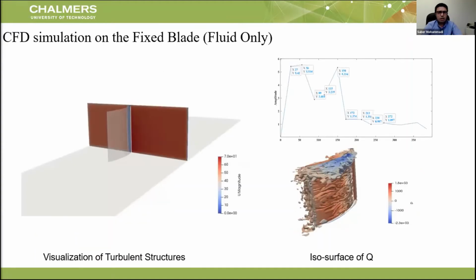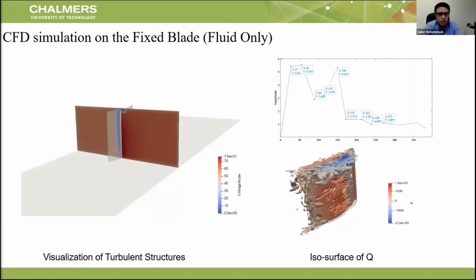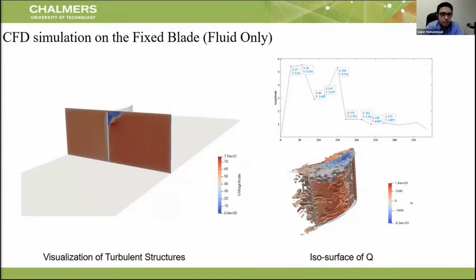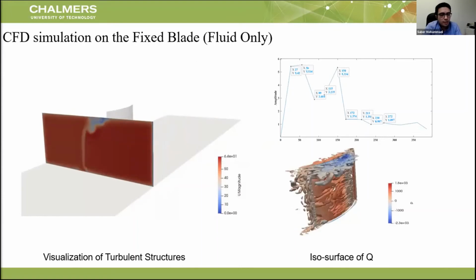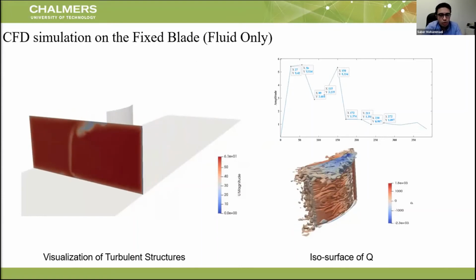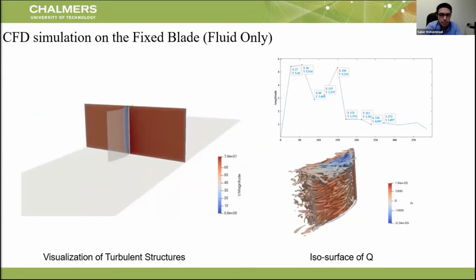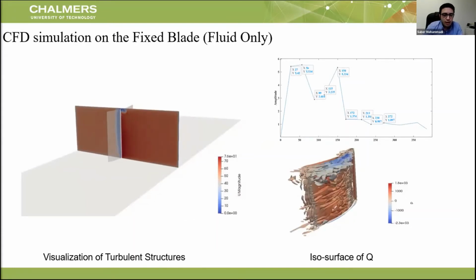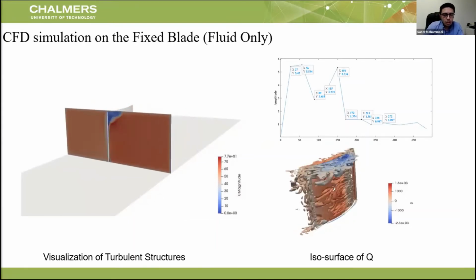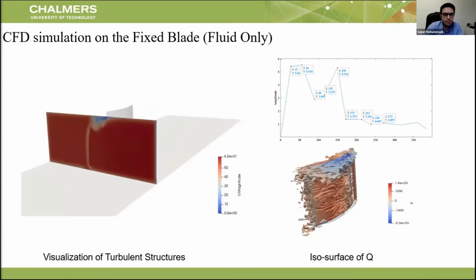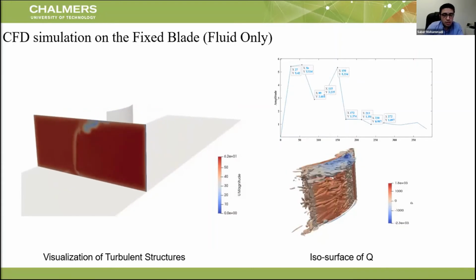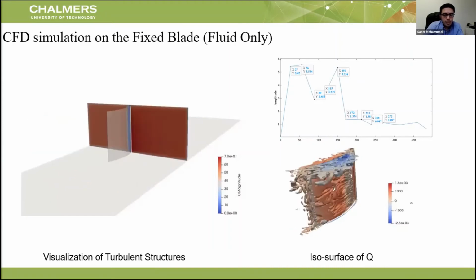We started with a fluid-only simulation using solids4foam to be able to get some information about the flow and also vortex shedding, to have a better insight into our problem in the FSI part. It is obvious that we are having separations at the backside of the blade, close to the tip and also behind the trailing edge, which would be the sources of vibration.